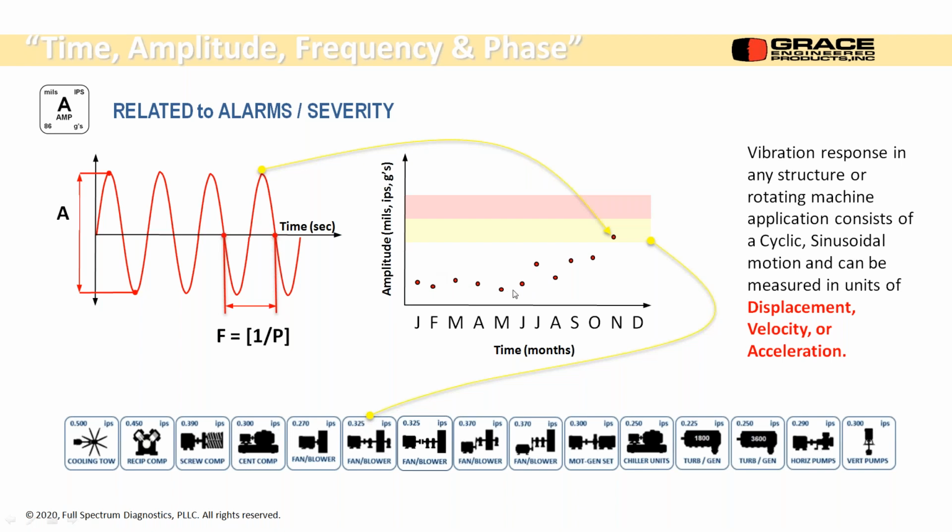But if you have a transducer that's magnetically mounted to the machine and staying put all the time, you don't have any of that manipulation. This might be actually some type of fault that popped up that's very subtle that we'll be able to get when we start filling in these dots with more data. So even though we're not getting a lot of frequency information or any frequency information until we do a spectrum, the amplitude's got a lot of stories to tell. So we'll worry about that a little bit.